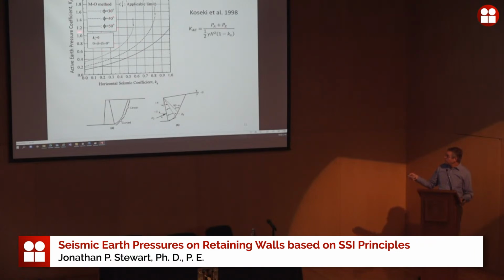There's a number of geometric variables defined here, which are given down here. It's the angle of the backfill, the angle of the wall to vertical, and so on. So if we were to come in here, for example, at 0.5 G, you can get numbers of 0.4 to, say, 0.9 or so as the horizontal pseudo force. That's a pretty strong one.